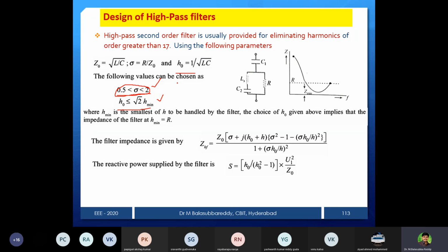You give inputs voltage and current, and the output will give real and reactive power. Now see, without compensation, you load something, you can give some source, 3-phase or single phase, anything. What is the source real power and reactive power? What is the load real power and reactive power? So the problem will arise only in the reactive power. It may not be the same, based on your load. Suppose it is a resistive load, nothing will happen. But if you use an inductive load, what do we need to compensate: whether I need to generate the reactive power to compensate, or I need to absorb the reactive power to compensate.